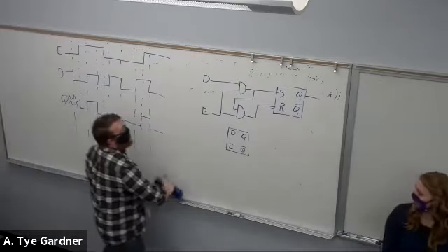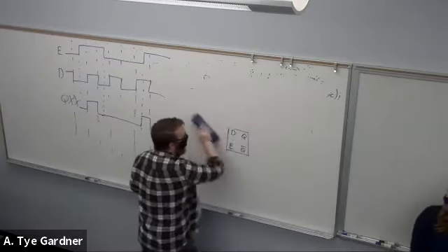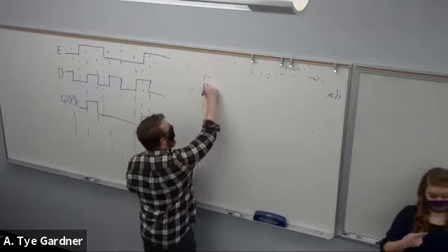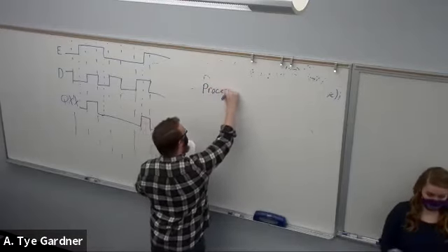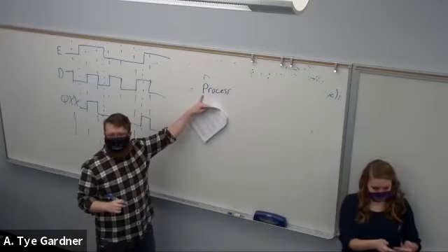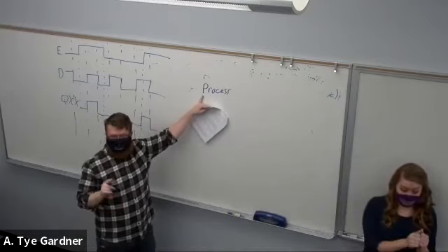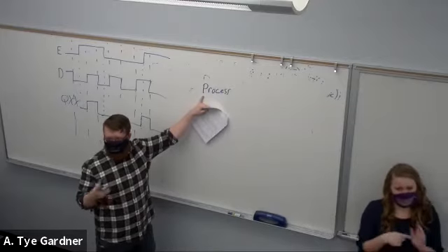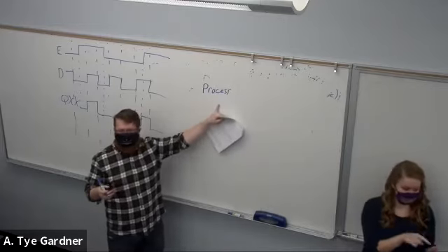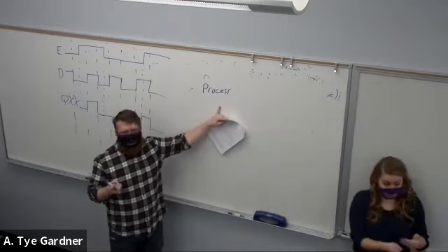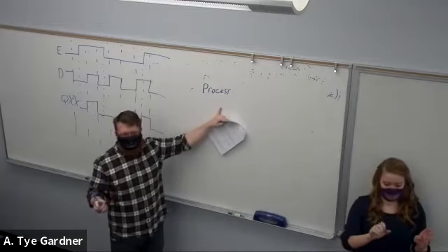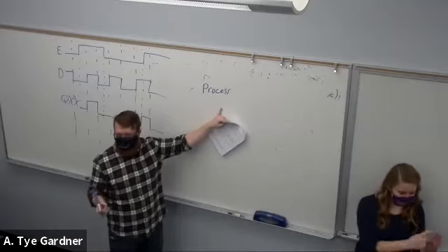Okay. The D-Latch in VHDL is actually really easy. So we've seen this before, process, right? But we've done it only in test benches, really. I showed it a little bit when I first introduced VHDL and muxes and those kinds of things, but now we're going to get into it a little bit more. A process is your main indicator that it is sequential logic, meaning it happens in order rather than fully parallel, as is the case with combinational logic.